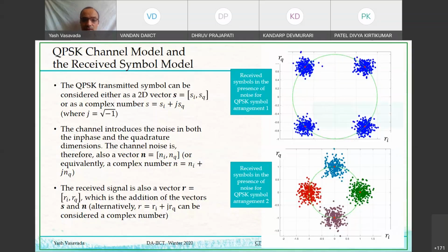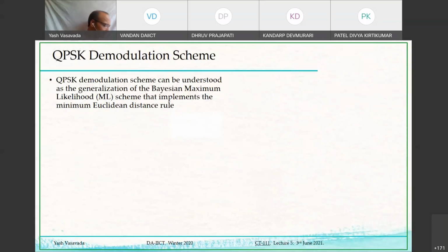So now we can again do the minimum distance decoding. And this again assumes that all these 4 symbols of QPSK are equally likely. That probability is 0.25. So assuming that all the four symbols are equally likely, which by the way is also a corollary of Q being 0.5 for X incoming bits: if the zeros and ones are equally likely, then all four symbols will also be equally likely.